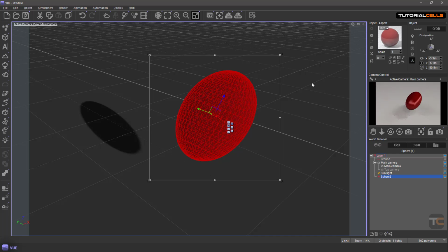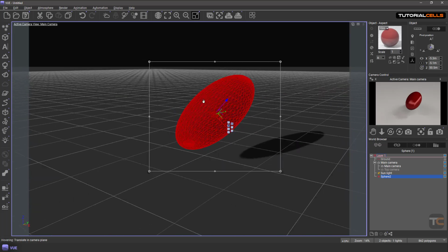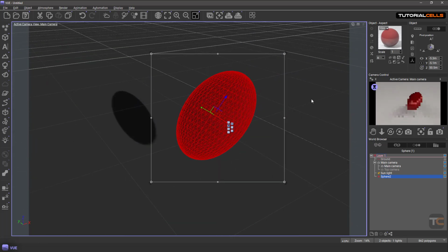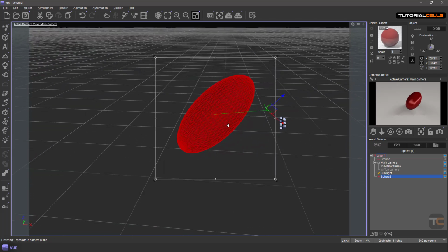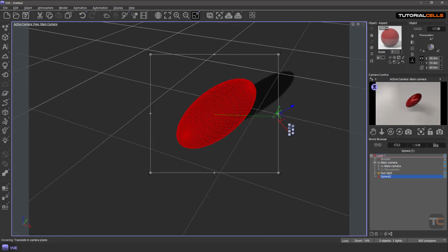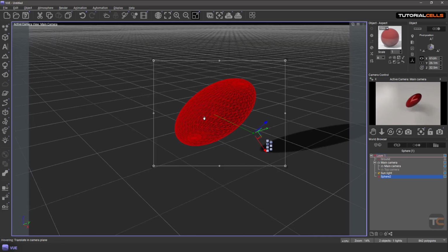And the most important thing here is the pivot. The pivot is the center of the object. You can see it's the center of your object. If you want to change the pivot of your object, since it rotates and moves based on center, turn on this eye, and this blue dot will appear here, and you can move the pivot. Make sure that you are snapping to your object. Click it, and you can change the object's pivot.